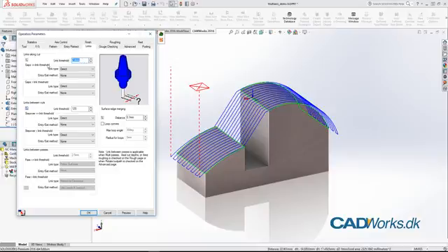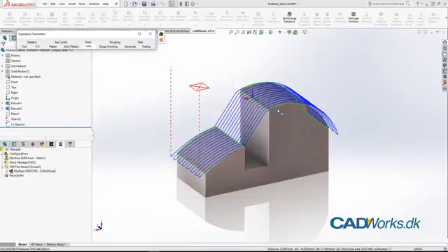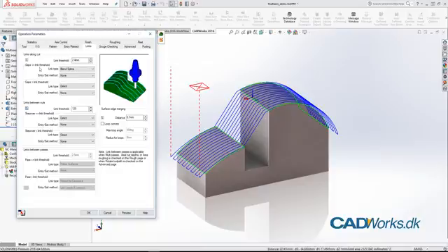And if the link threshold is less or equal, then we are going to use this group. If it's larger than the 2.4 millimeters, then we are using this group. And from this point right here to this point up here, there are more than 2.4 millimeters. So if I set this one to blend spline, it is not going to change anything on this part because we are above that gap. So I'm going to go for the larger gaps and then try setting these.